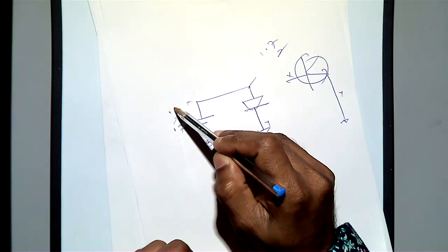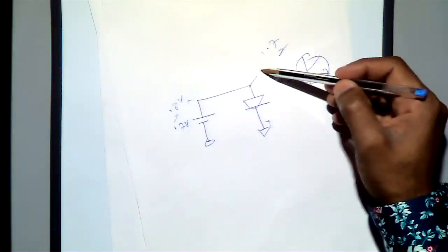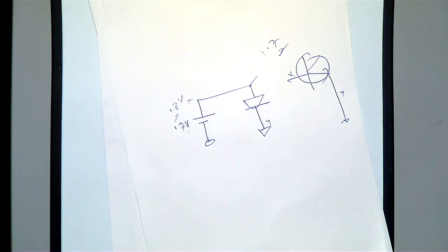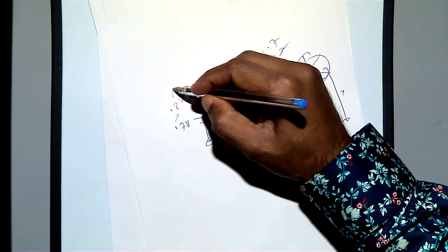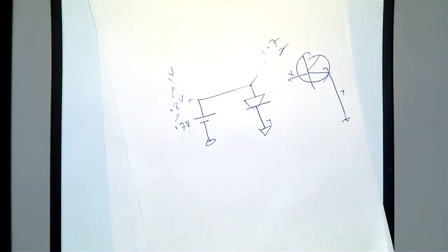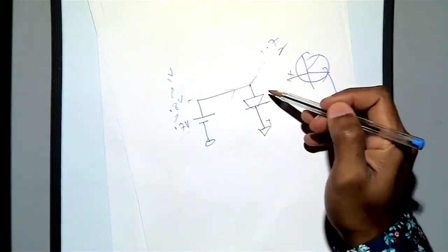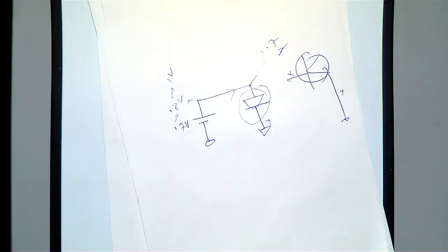How about an exaggerated value? I put 0.8 volt. How much will you get? If the diode drop is 0.7, how can you get 0.8? Again, exaggerated, 1 volt. You won't get 1 volt, because the diode makes sure the drop is only 0.7 volt. Then what happens to the remaining voltage? It will increase the current and burn the diode. That is the reason that when you increase the voltage, the diode burns.